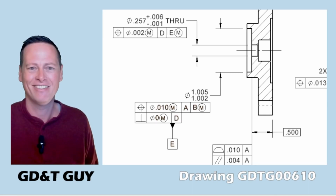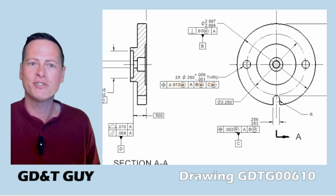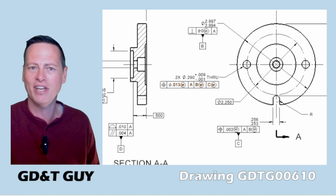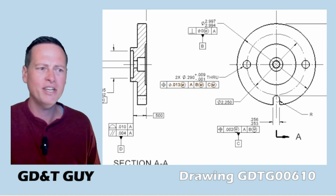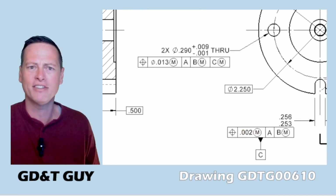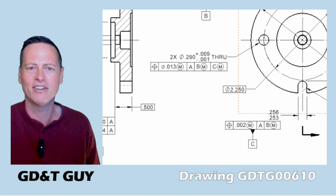No problem. But we do need the datum C tertiary in the position tolerance of the screw clearance holes though, don't we? Because the pin and slot are going to work to constrain this interface in rotation. We need to control the location of the holes, not only to datum feature A and datum feature B, but also to datum feature C, the slot here.